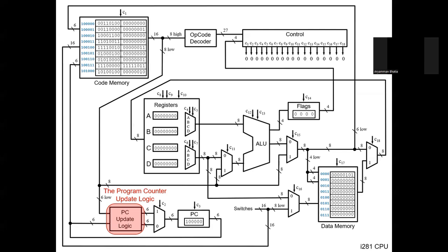But at times, for example, when we are executing a loop and we want to go back up to the first statement, we want to jump to a new step, in which case we need the address of that particular register in the code memory. Which of these two we want to do is controlled by the control line C2, the multiplexer corresponding to that.